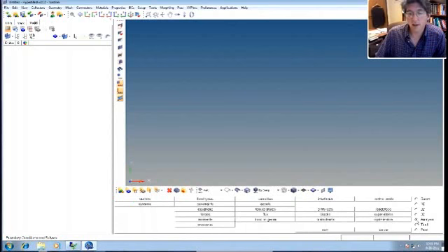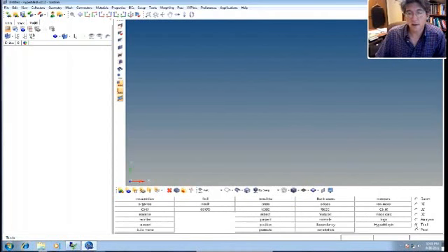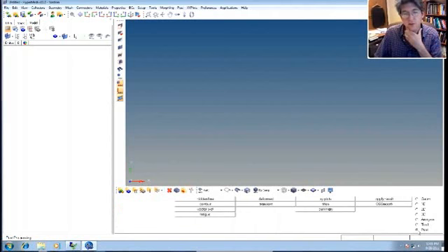If I click the analysis radio button, this gives me functions that let me define load steps, forces, constraints, which are SPCs, and other types of control cards. Then you have another one that's tools. This lets you do things like edit, delete, and move things around. And then once you have a solution, you can do some post-processing in here, actually look at the results.